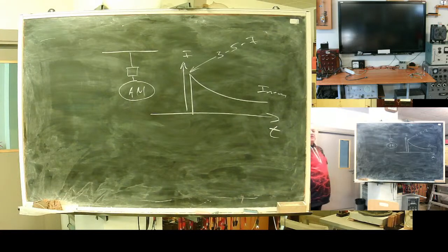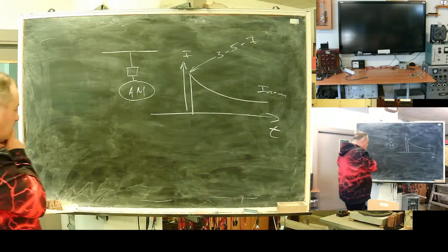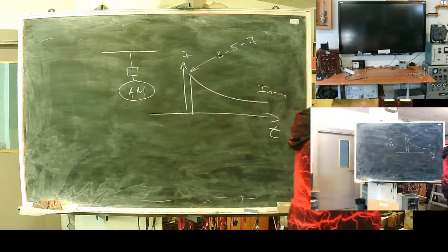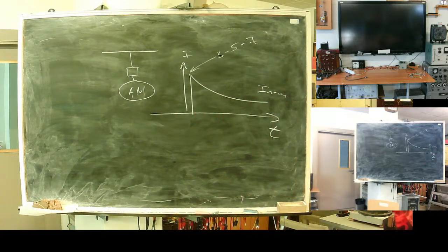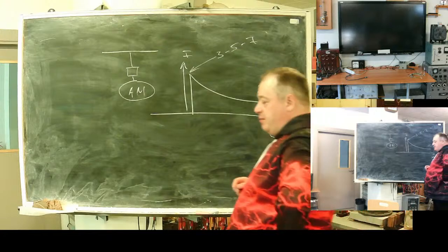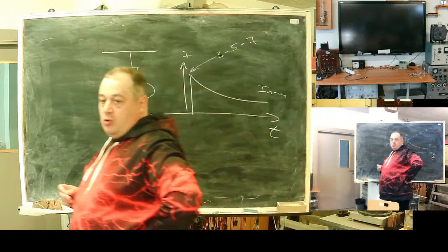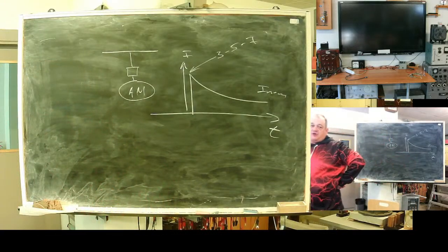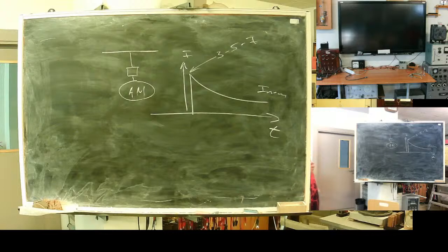What kind of protection would you like for this machine? On the one hand, it should disconnect the motor in case of internal fault. It's clear, but that's not all. You also would like to protect it from overload damage.